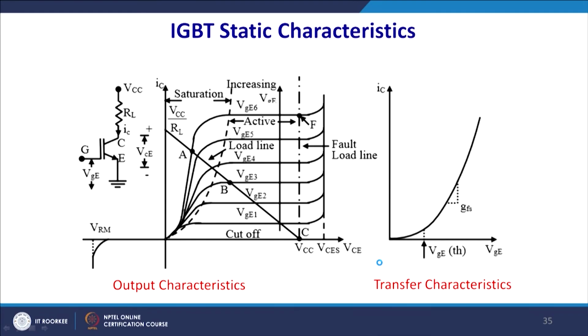These characteristics are the same as the characteristics of the BJT, which you have studied in normal BJT applications in your analog electronics. So, this is your load line, and this is the IC and VC, and for the different curves, instead of IB you will have the gate voltages. This is the only change. So, you will have this transconductance. Accordingly you will have a VG, and this is the current IC for the different values of VG, and this region is the saturation region.